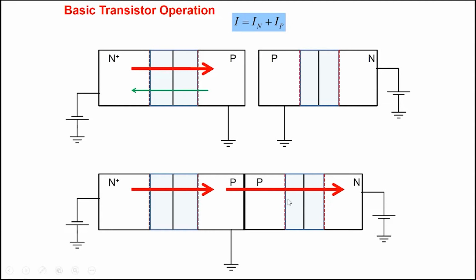So this is very interesting, because note that this is a reverse bias junction. We just said it's a reverse bias junction, and in a reverse bias diode, we expect very little current to flow. But we have to keep in mind, why does very little current flow? Very little current flows because there were very few electrons in the P region. But now that we have connected a forward bias junction, this forward bias junction injects a lot of electrons into the P region, and therefore a lot of current starts to flow here. On the other hand, this component of the current remains as it is here. So note that we said that these electrons are about 100 times stronger than this particular part here.